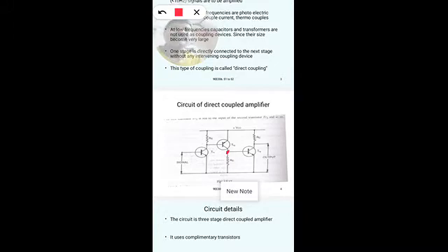One wire acts as positive and another wire acts as negative, and the air gap that exists at the joining of the two wires acts as dielectric. So this is called stray capacitance or wiring capacitance. That will come at very high frequencies.